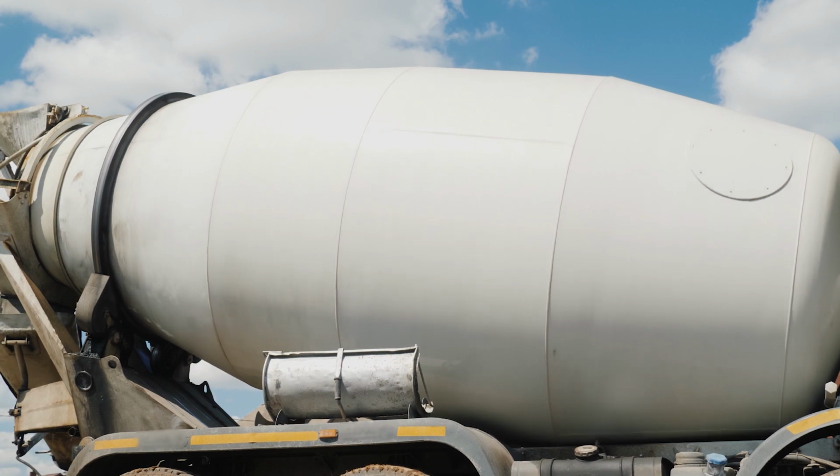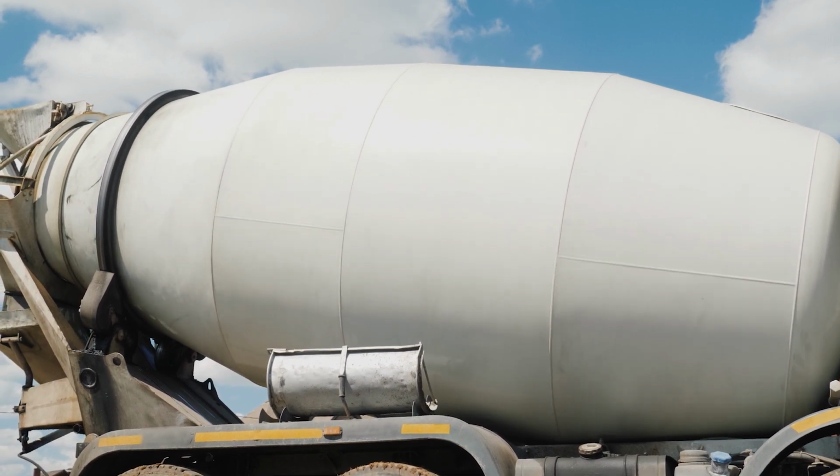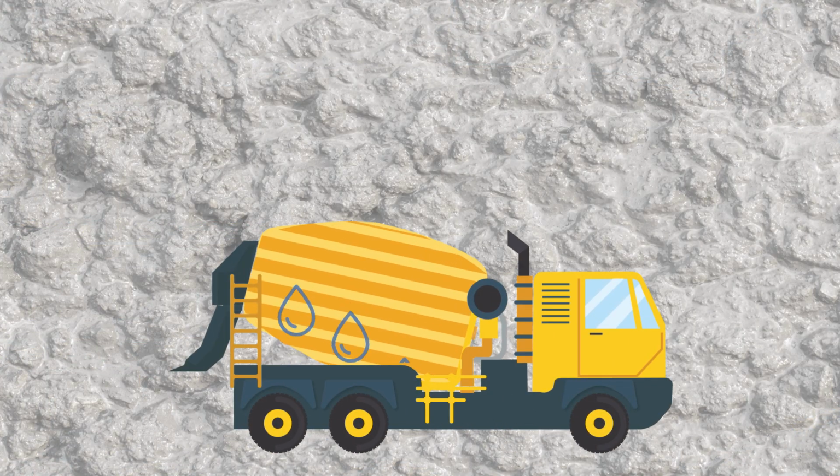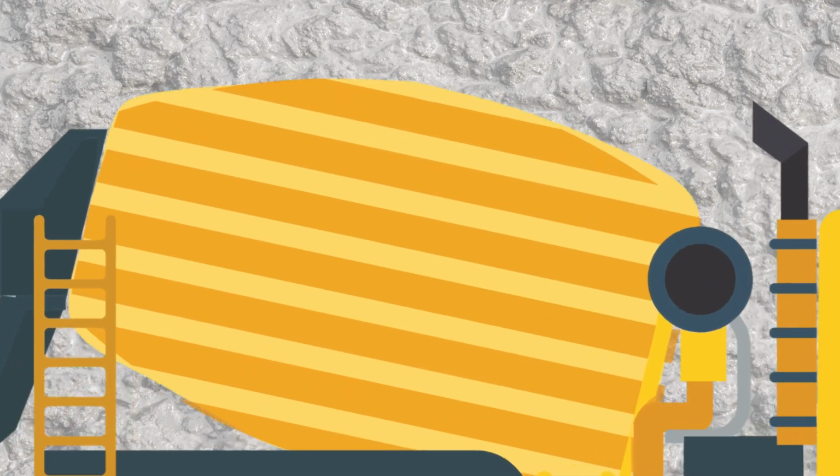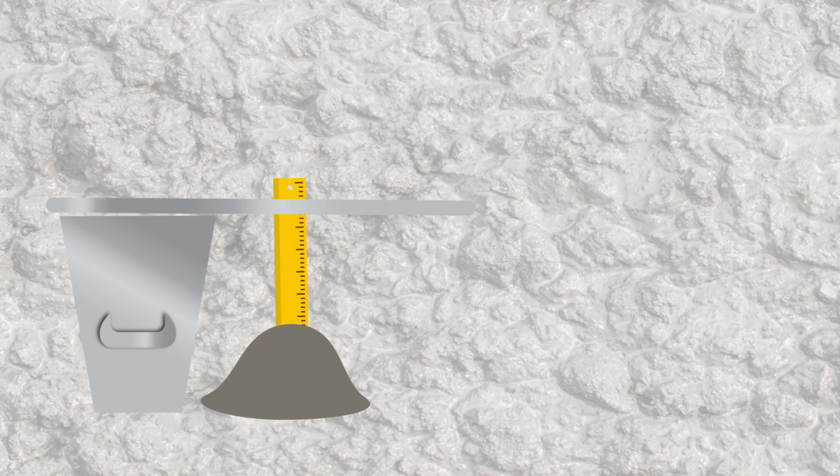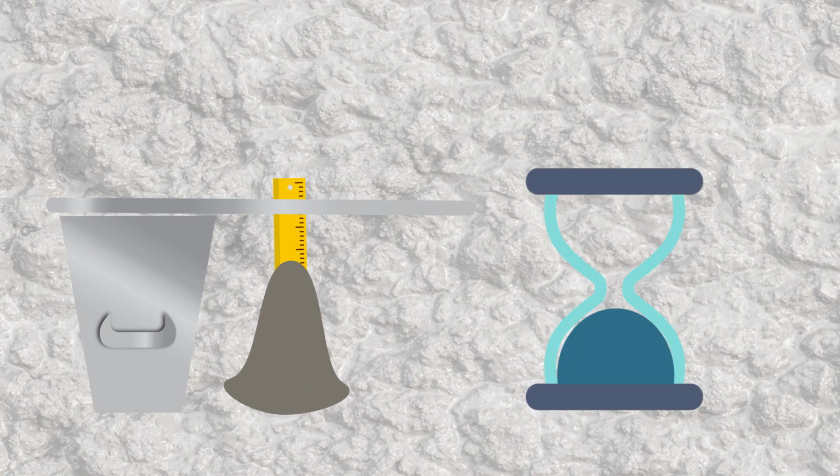Concrete slump decreases the longer the load is mixed. This is due to water evaporation over time and the development of fine materials as the coarse aggregates are worn down during the mixing process. Some tests showed a nearly 6-inch slump loss after 60 minutes of additional mixing time.